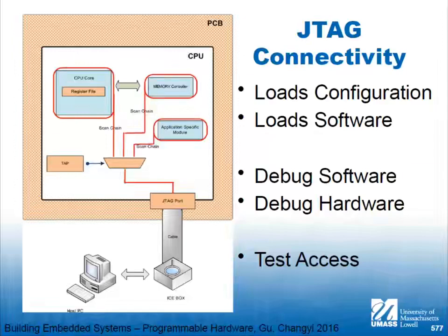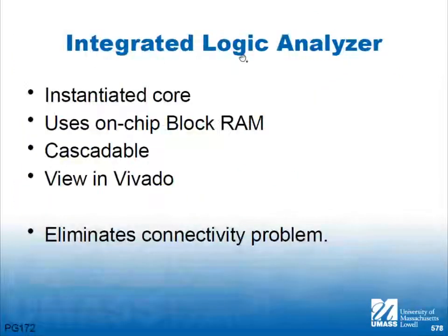Now, how do we debug the hardware? With logic analysis. And when we do logic analysis, we have to have good connectivity. And we're going to have good connectivity because we're debugging it from inside. So that gives us flexibility in connectivity, and it gives us full bandwidth. Full bandwidth meaning we don't have to worry about probe contacts, 1 meter cable, connection to an oscilloscope or logic analyzer, internal amplifier of said device, right? So we've solved all the problems that I've set up tonight with this JTAG connectivity and an integrated logic analyzer.